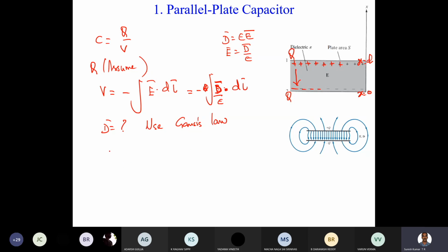If you take any plate, from the boundary condition for electrostatics, electric flux density will be equal to rho s, perpendicular to the boundary, the plate carrying the charges. Hope you recall this. The electric flux leaving a surface equals rho s. This is actually the easiest approach.